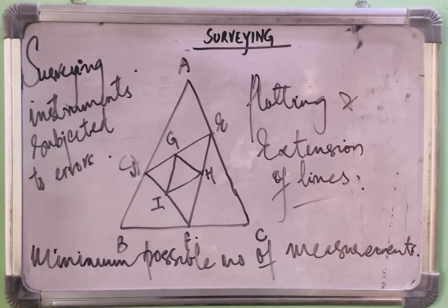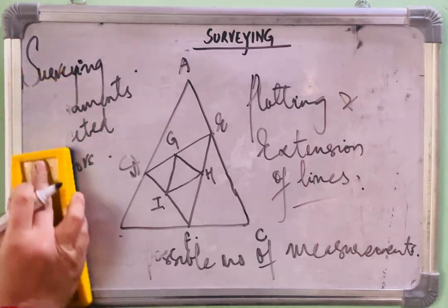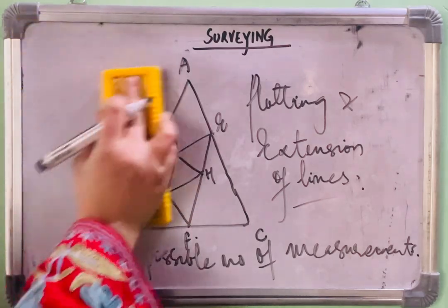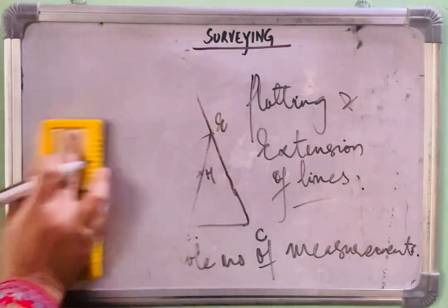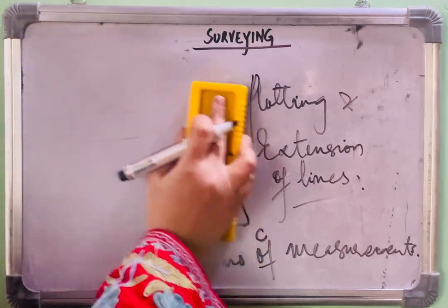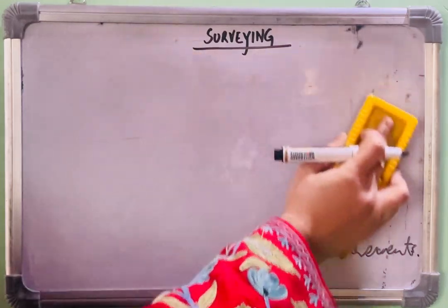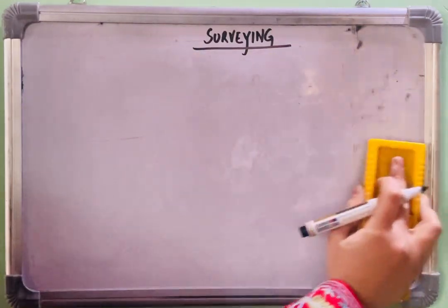And the measurements of a subsidiary framework can be established by relatively less accurate surveys, right? So this was about the first principle of surveying. That is, we have to always work from whole to part, and by doing so, the errors are localized and the accumulation of errors is controlled, right?